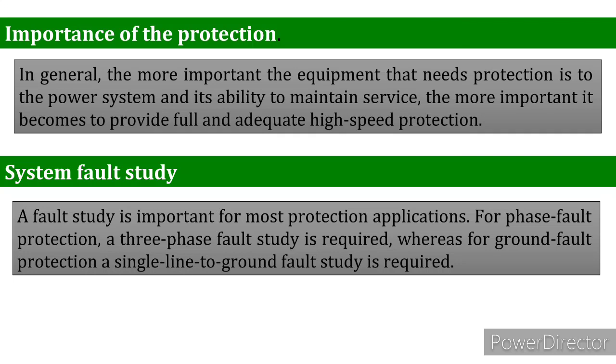Well, importance of the system equipment that is being protected. This is often apparent by the system voltage level and size. For example, a high voltage transmission line is usually protected by high speed pilot protection, and the low voltage system by time over current protection. However, this should be clarified according to the desires of the protection engineers or the requirements of the systems.